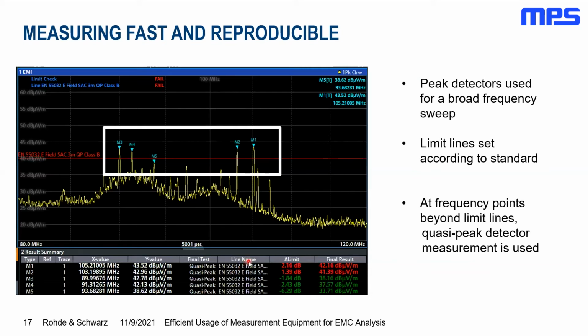So typically we start the measurement using the peak detector and measure the peak against the quasi-peak threshold. And as we've learned previously, the quasi-peak will always be the same as the peak or below. So vice versa, if the peak value is below the quasi-peak threshold, we don't have to repeat the measurement with the quasi-peak, because the quasi-peak will be below the value we have already measured.